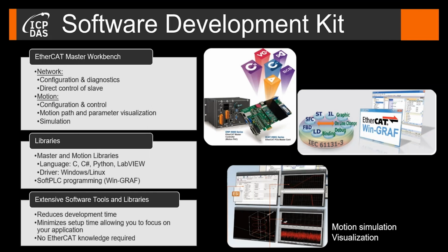It supports single and multi-axis motion testing. Basic motion functions such as point-to-point motion and interpolation can be directly commanded using this utility. In addition, this utility contains graphs for tracking the path of the motors and for plotting the motor velocity and acceleration values over time. Further libraries for accessing the EtherCAT network and motion controls are provided. The libraries can be integrated into all standard Windows and Linux programming languages. Plenty of demo programs are available, and no in-depth EtherCAT knowledge is required when using our libraries.